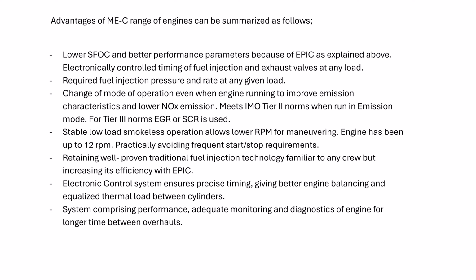We are still carrying out decarb much earlier, basically around 15,000 hours approximately. Dry dock to dry dock is also being done by people, depending on the hours the engine is running. But dry dock to dry dock overhauling of the units is feasible. Much less work for the ship staff.